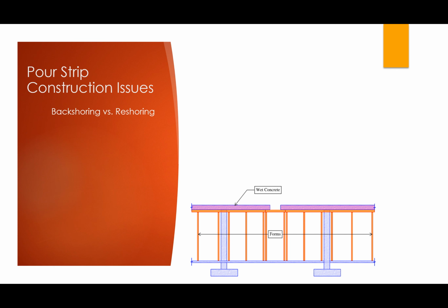So here we go. The contractor has just poured level 2, so the concrete is wet. It is not self-supporting. This is before the post-tensioning, and there's just formwork going down to the ground. And obviously that formwork just has to support the wet weight of the concrete. Nothing particularly interesting here. But let's fast forward in time just a few days to when that concrete cures enough for them to post-tension and then for them to go ahead and remove the formwork under level 2.